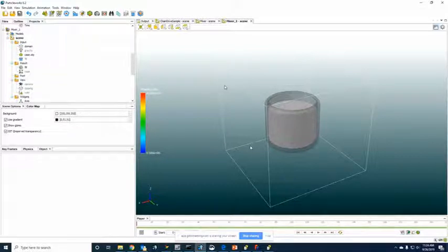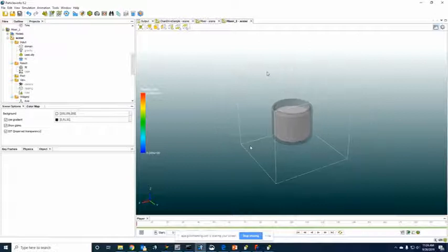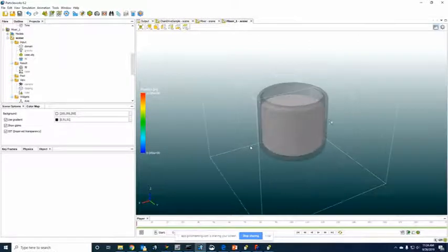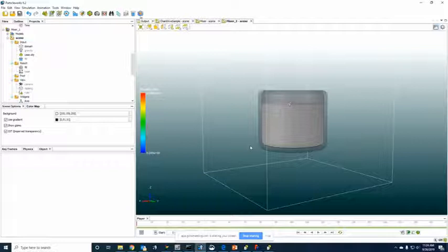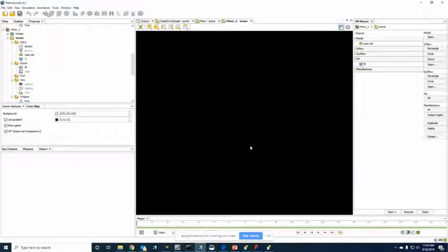I start with a new Particleworks model, and in this case, all I have in this Particleworks model is this tank and this fluid. This fluid's filled to a certain location. The fill is fairly easy to do in Particleworks. I like to use what's called the wizard in Particleworks, and the wizard will walk you through the normal steps of how to run things.